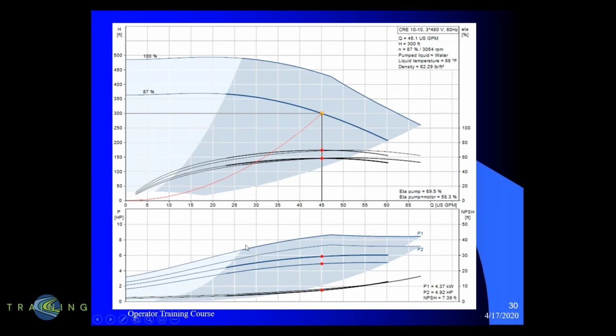One more on sewer pumps. Why do they say they won't clog, and they clog very often? That's a great question. I wish that it wasn't so easy to clog a sewer pump. A non-clog pump means that its purpose is to pass solids, but especially in today's atmosphere, with a lot of people struggling to have the right type of toilet paper, many people are flushing things that don't need to be flushed.